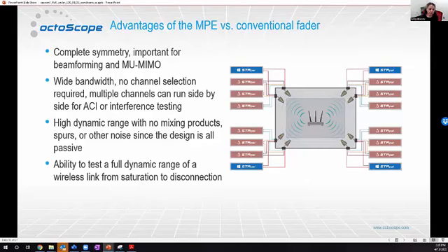And then do we have special control? We do have control. We have actually a lot of control over PAL 6. It's based on the Hawkeye chipset. We have access to the firmware and all the registers. And we turn the PAL 6 into an instrument. And we'll be showing some of those capabilities. So we can control things like MCS, number of streams. We can emulate virtual stations using PAL 6.